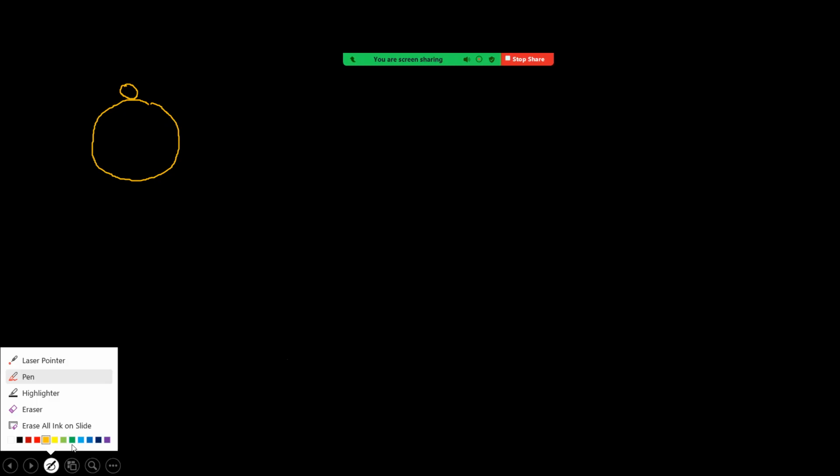It is now a sphere. We are placing that body on the sphere like this. And if you are taking the condition just without wetting, it means it is now like this. It is just inside. This is now the limiting condition. So again writing the condition here, volume. First I'm writing here, weight of both the blocks is balanced by buoyancy force.